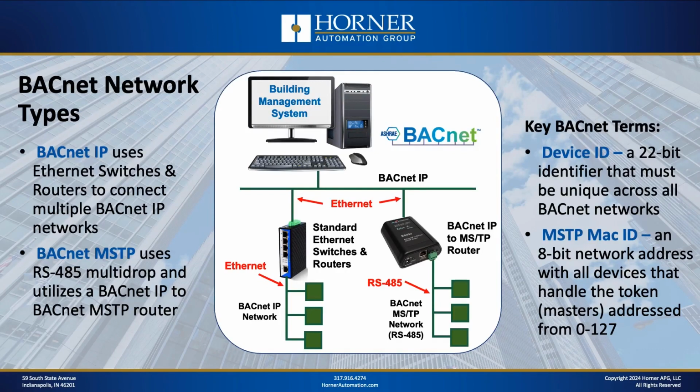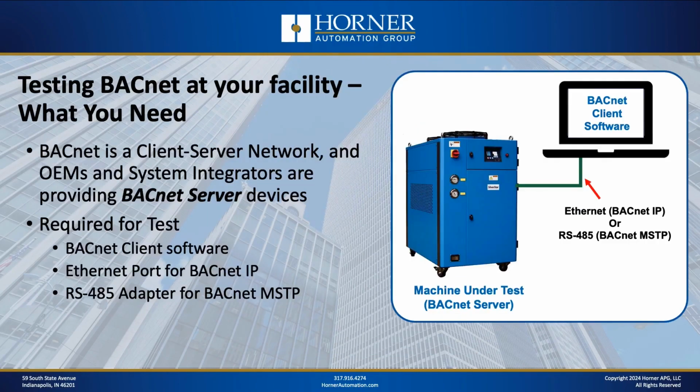Now, what are you going to need at your facility to test your machine over BACnet so that when you install it at the customer site, you've got a pretty good assurance that things are going to work the way you want? Well, BACnet is a client-server network. That's the model it uses. And typically, OEMs and system integrators are providing equipment that is going to act as a BACnet server, okay? Which means if you're going to test that, you need BACnet client software to do the testing.